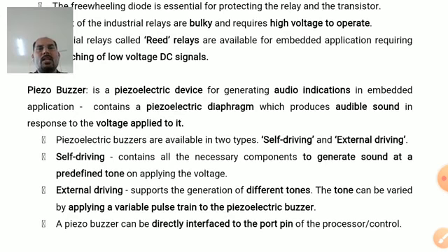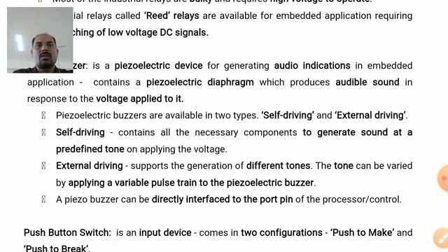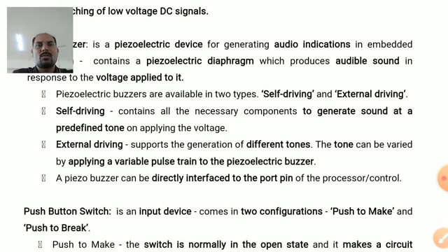It is a piezoelectric device. The piezoelectric device works on the principle of mechanical and electrical effects. It means that whenever we apply mechanical input to it, it gives electrical output, or whenever we give electrical input to it, it gives mechanical output. And this piezoelectric buzzer is used for generating audio indications, and it contains a piezoelectric diaphragm which produces audible sound in response to the voltage applied to it.